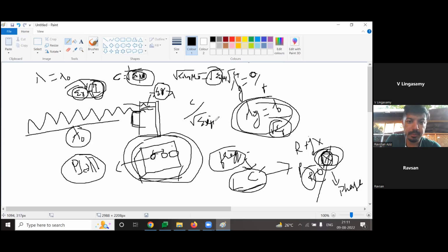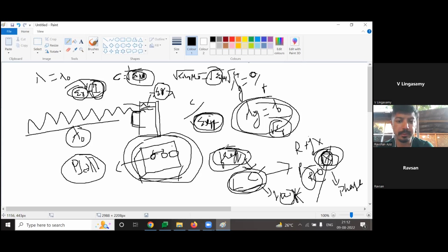When you control this parameter, indirectly you are controlling the frequency as well as the L and C, because L and C are represented in terms of j omega something like that, right? Sorry, j omega something like that. Therefore, by controlling this effective dielectric constant, I am indirectly controlling the frequency to be passed, not passed, or reflected with some phase, which means L and C are playing a role, and therefore I can control this phase as well, apart from the magnitude.